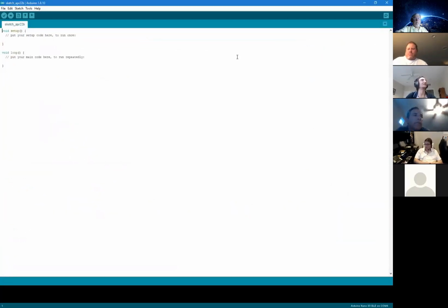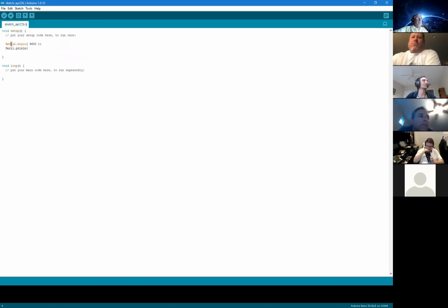This is the Arduino IDE. And traditionally, you would work with it doing something like this. You say Serial.begin(9600), which is the speed of the serial, and then you'll say something like Serial.println. Something like this, right? And if you want to set a certain port to high or low, you will do things like, let's say port 13, and you say I want to set it to high.